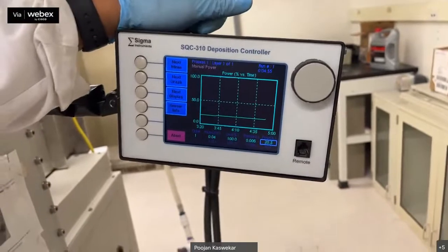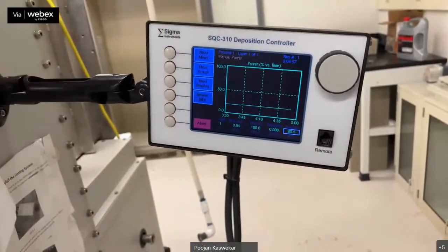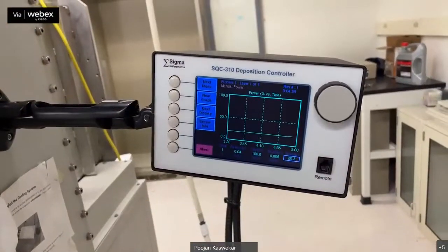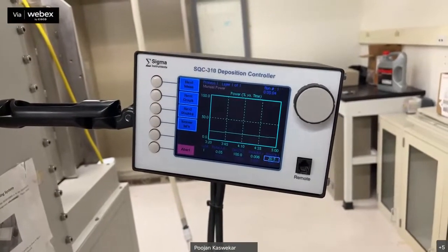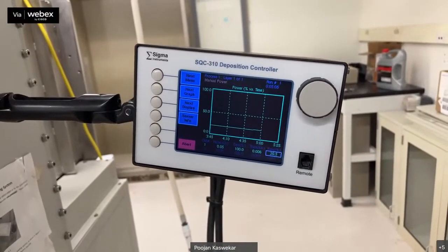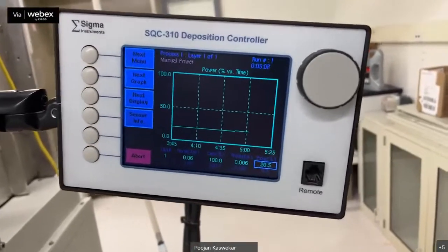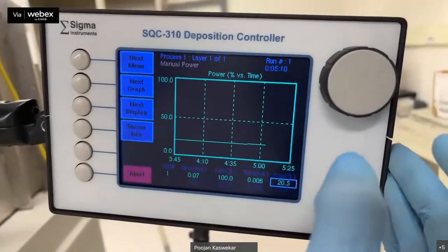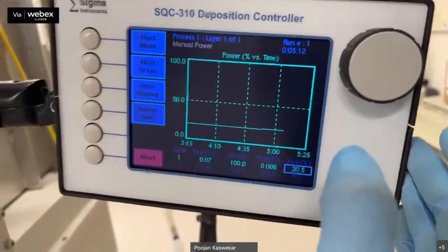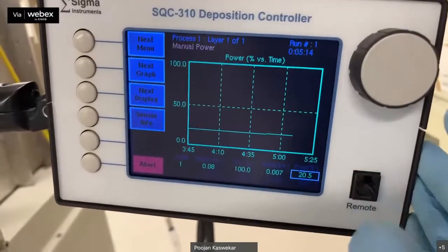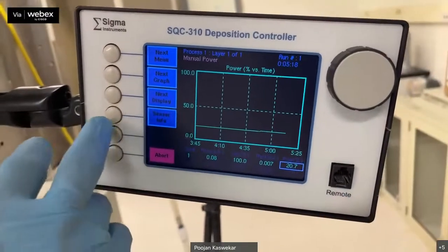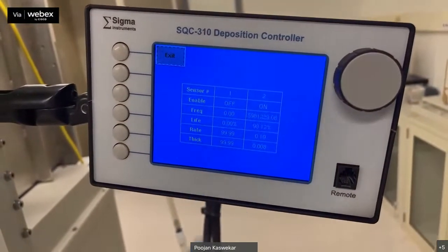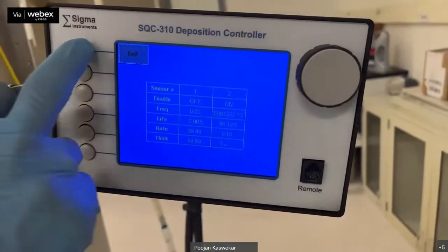So the more mean free path you create for the electrons, the less pressure you have, and the more time it will take to deposit the silver on top of your cell. But a lesser mean free path is bad because it will create more contamination in your cell. So now it went to 0.1 angstrom.